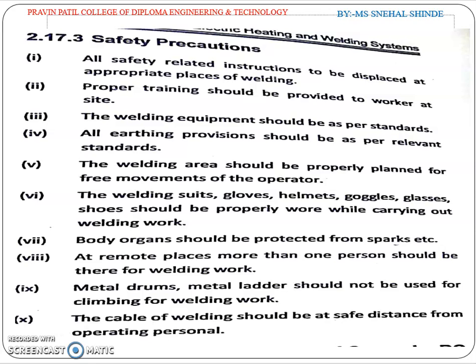So it is recommended that more than one person should be there for performing the welding work. Then metal drums and metal ladders should not be used for climbing for welding work.